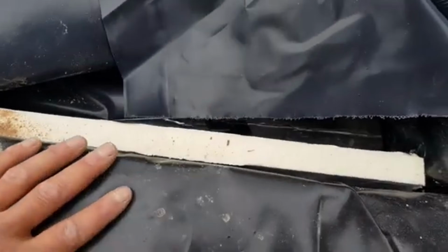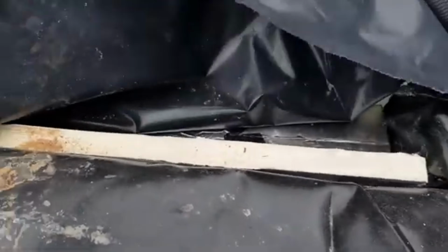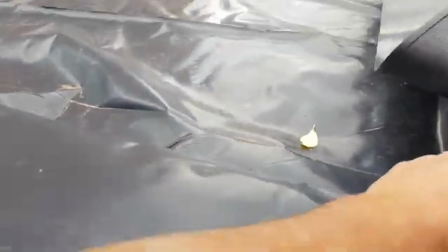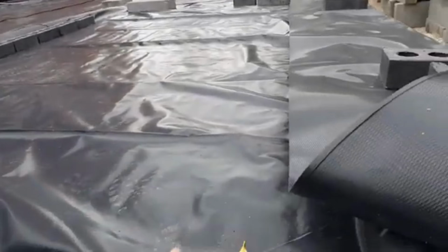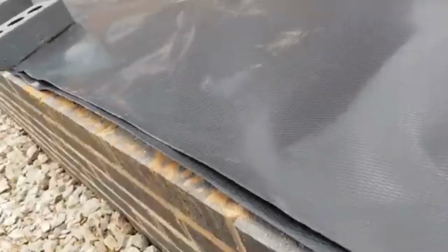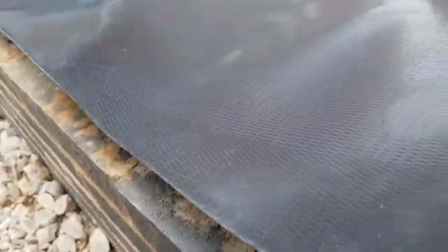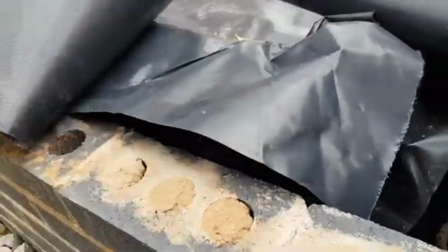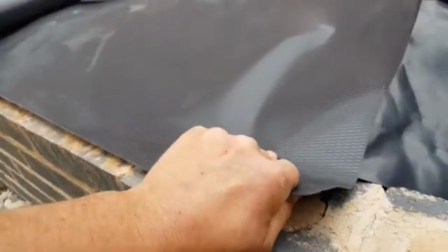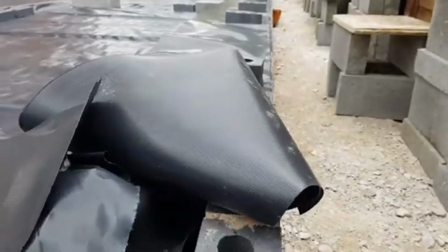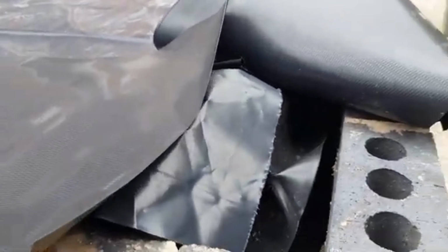Ensuring that these steps have been done correctly will save you a lot of money in the future on repairs. Here are key steps that you should follow. Install a proper DPC in all load-bearing walls. Install a DPM under the entire floor slab. Ensure the DPM overlaps and connects with the DPC. Use good site drainage around the house. Avoid raising soil levels above the DPC. Ensure proper plastering and waterproofing.